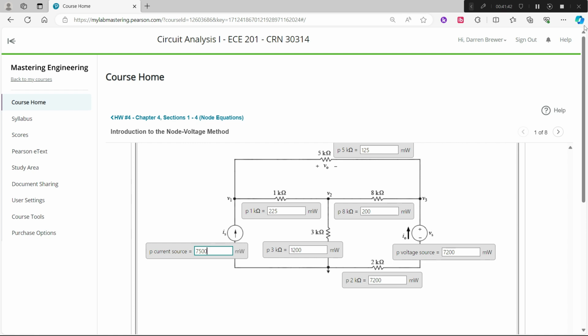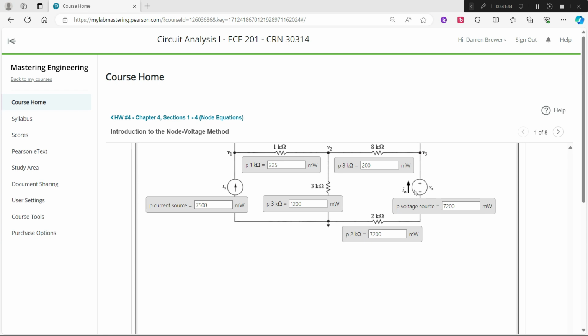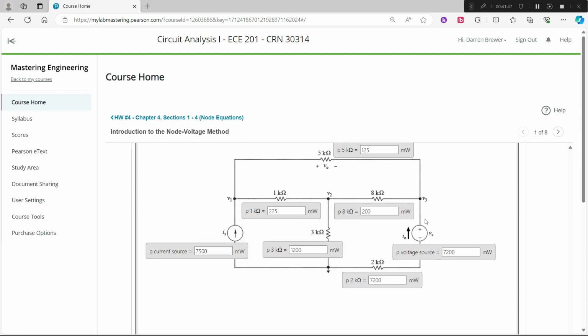Power at the voltage source, P2. Let me think. To be honest, I don't think we ever knew I sub 0, actually. The current, technically, should be 120 minus 100 divided by 2000, which is 0.01.